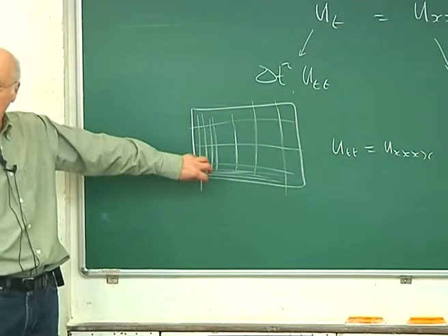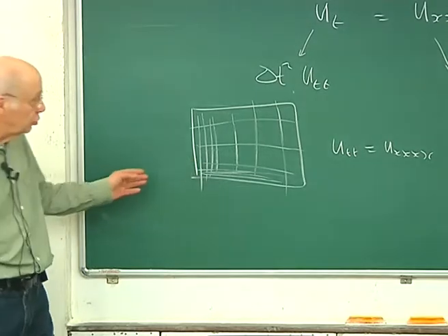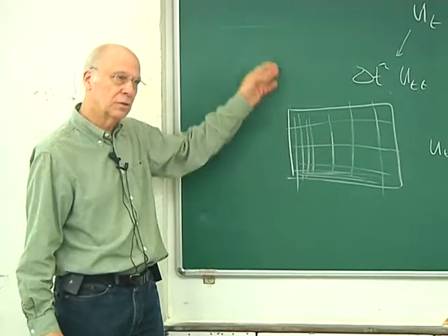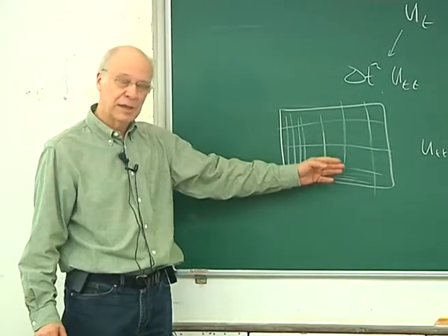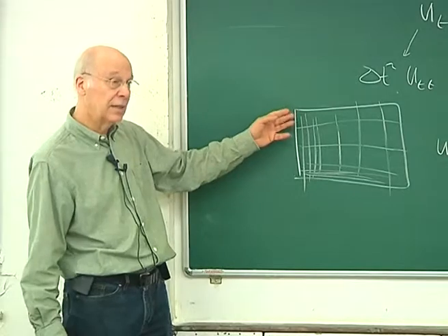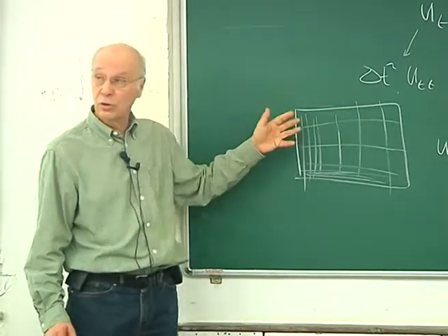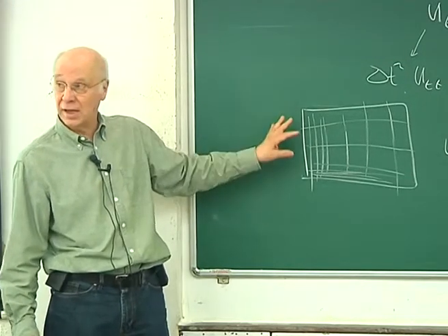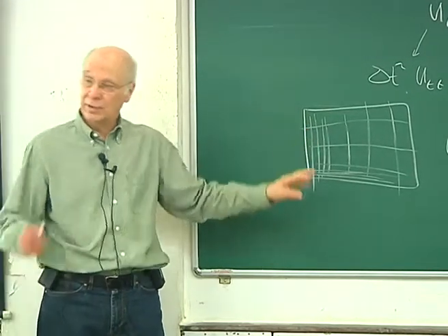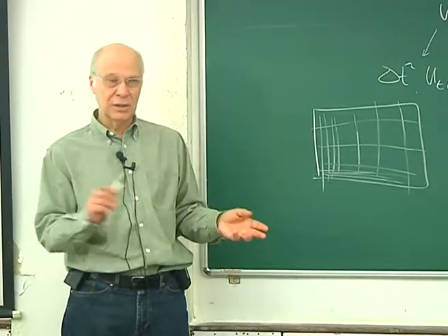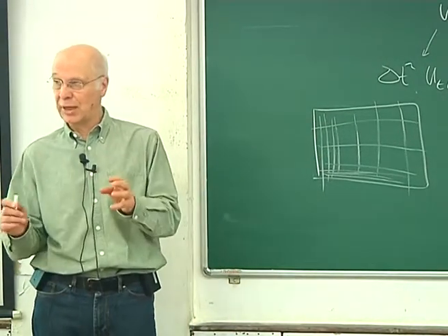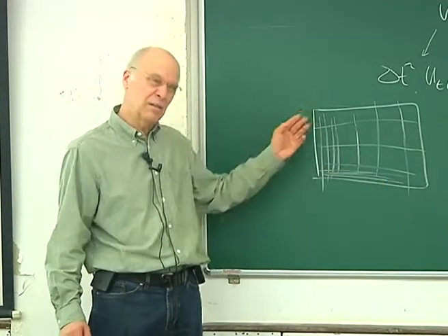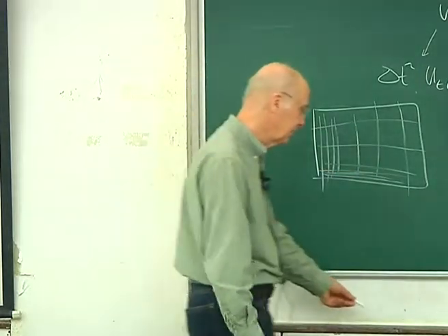In order to get a good resolution in this corner, we've got a good resolution all the way along there and all the way along there, and you may not want a good resolution there and there, but it's probably worth the price of having this. This is an orthogonal coordinate system, and it's equispaced in the transform variables psi and eta. So you have to weigh the advantages. Are you going to be nicely equispaced with second order accuracy, resolving things you don't want to know about? It may not cost too much.